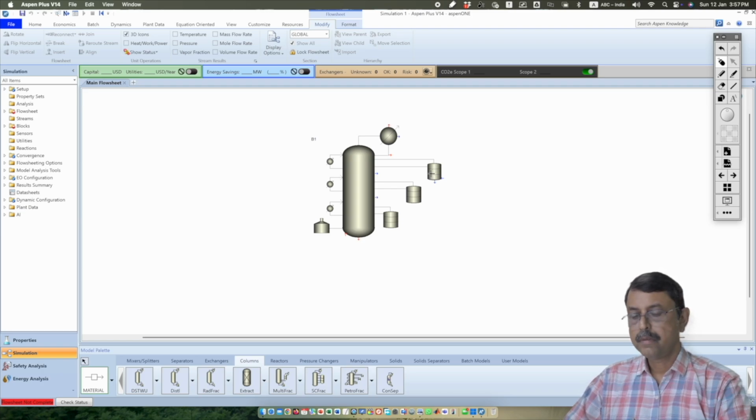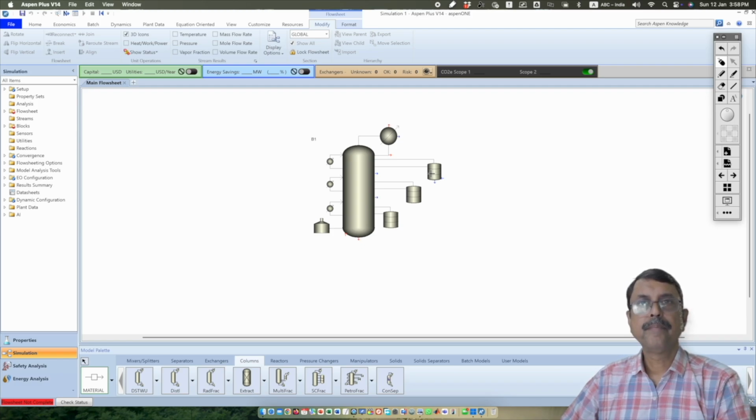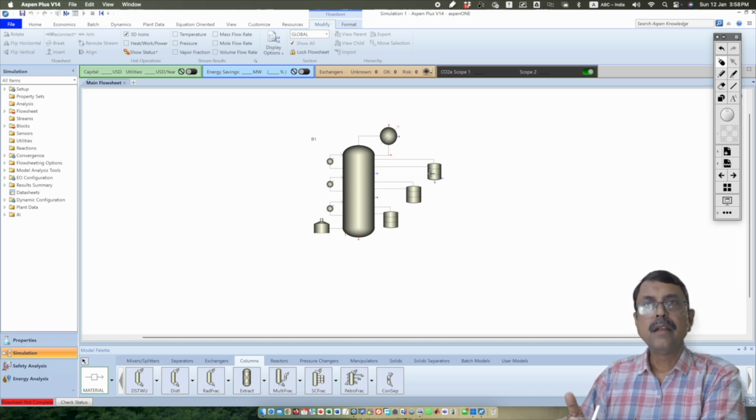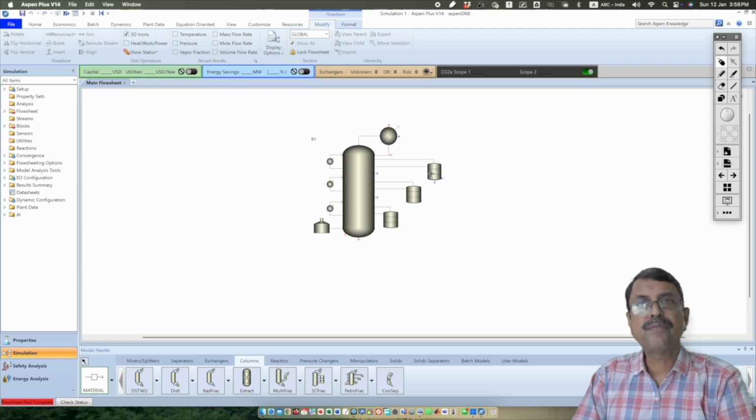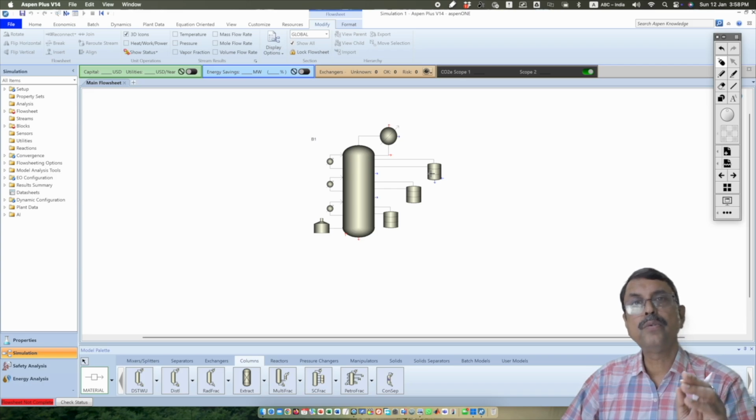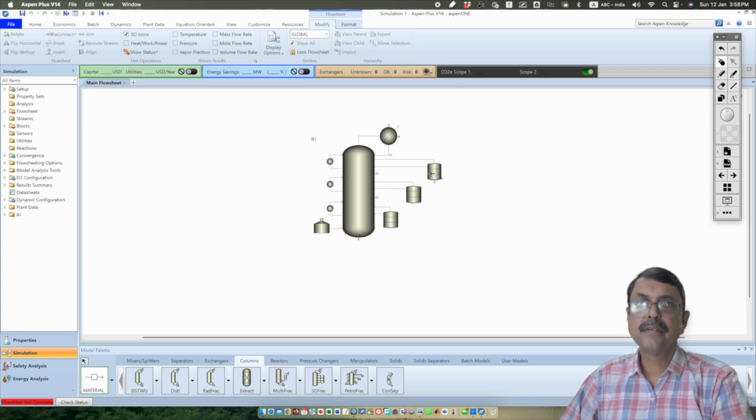Okay. So in the petroleum fractionation, you do not fractionate only at the top and the bottom. Rather, you may say that I want to extract the light gas oil or the kerosene or the heavy naphtha or light naphtha. So those are the different fractions that I want to extract from the distillation column. So it has given the option to use separate strippers in order to extract those extra streams out of the column.